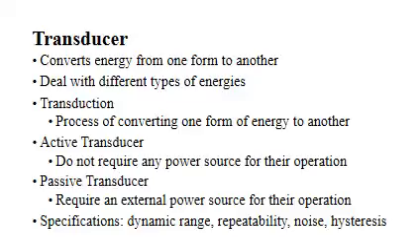For example, a photocell, that is LDR, is a passive transducer which will vary its resistance when light falls on it. This change in the resistance is converted to a proportional signal with the help of a bridge circuit. Then a photocell can be used to measure the intensity of light.